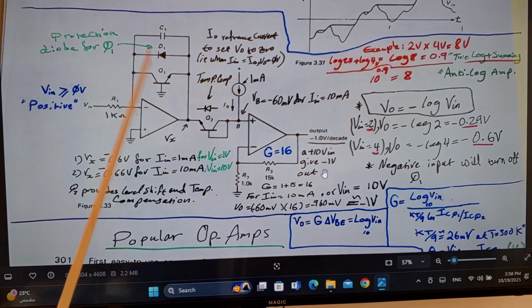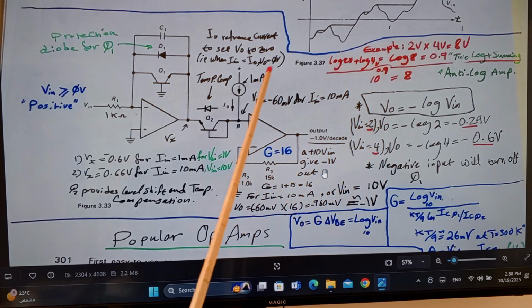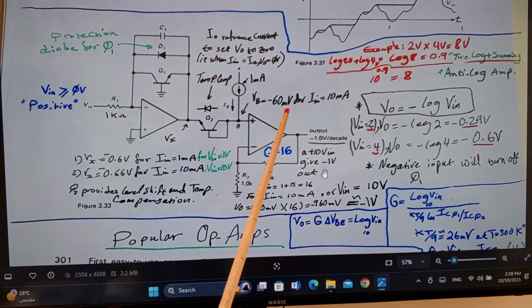And how do we do that with our circuit? We simply design the first log circuit, that one here for example. We design another log circuit, a duplicate of this one. We make this input number 1, we make this input number 2. And after that, we take the outputs of both of these circuits to a summing amplifier. It has to be a non-inverting summing amplifier where you can add both of these logs, to get your final output.